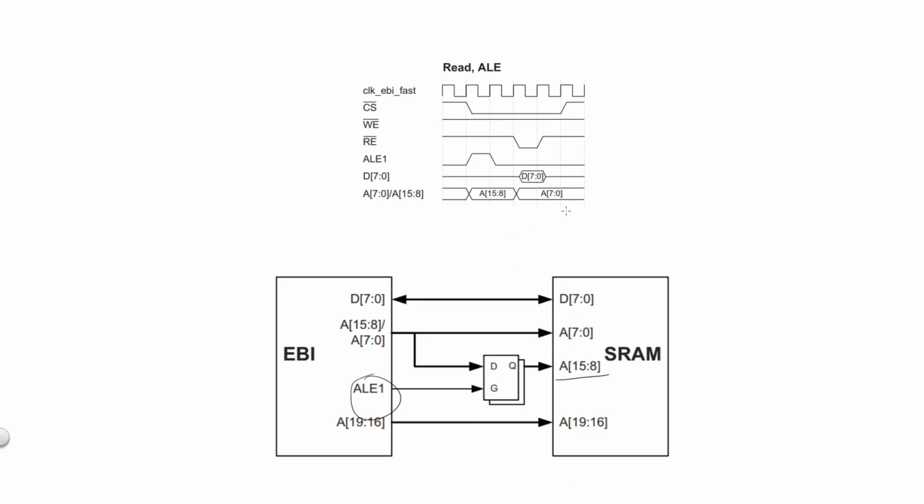Afterwards, the first address byte will be asserted onto the bus, and the second address byte will be present in hardware on the output of the latch. At this point in time, whatever data is on the data bus is then loaded into the CPU. Note that even though this setup is coined an SRAM configuration, it can still be used for a wide range of devices that have similar interfaces such as I/O ports, LCDs, etc.